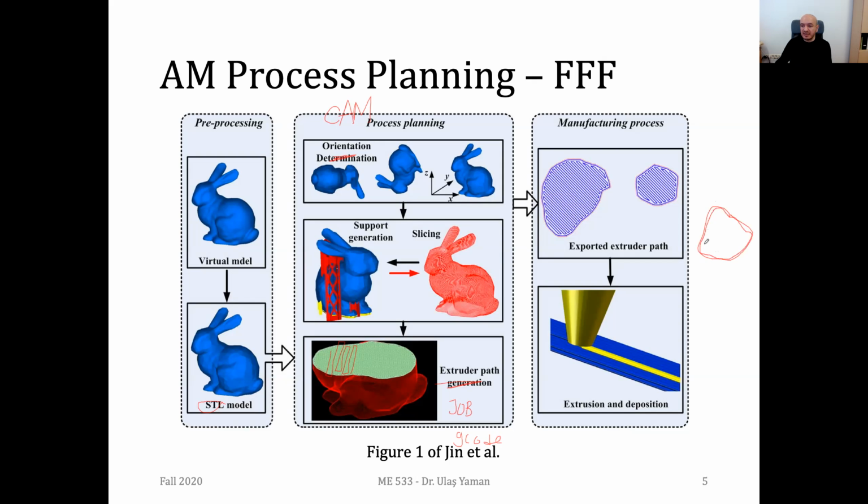You may increase it, but 2 or 3 is quite fine. And then depending on the settings, for instance, probably this infill percentage is 100%. But if you want less material inside, then you may have such a sparse infill. Probably this might be 30% or less.